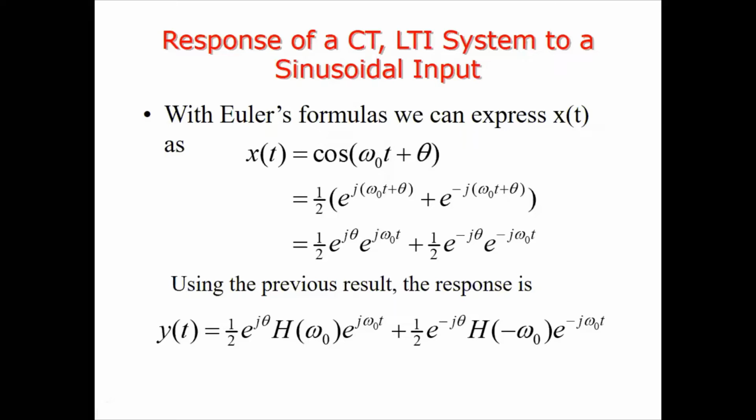If you remember the spectrum plot of a signal in your Fourier transform, we take 0 radians per second or 0 hertz as a reference point, and with respect to that, if you plot the spectrum of, say, one square pulse, you will end up with a symmetrical plot over the negative and positive frequency range. So in practice, we never apply a negative frequency, but it is only for a theoretical understanding of the distribution of the spectrum.